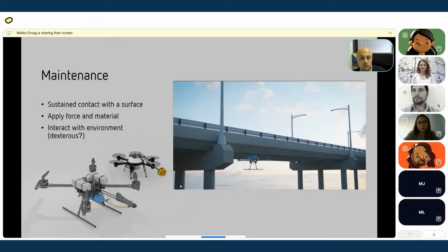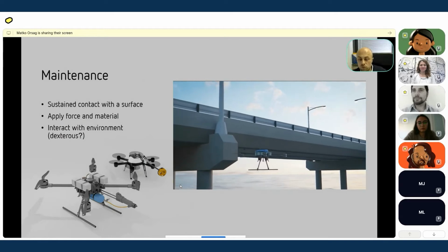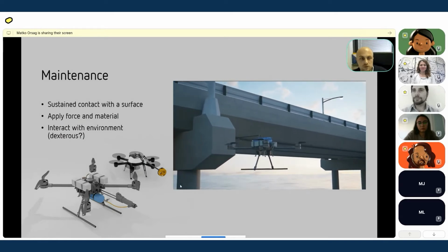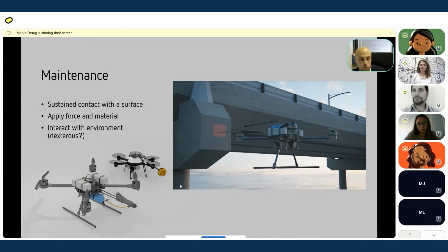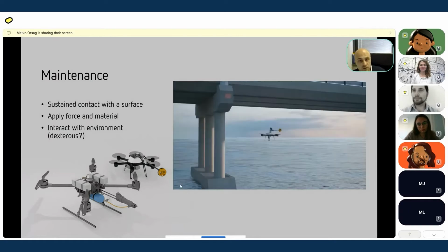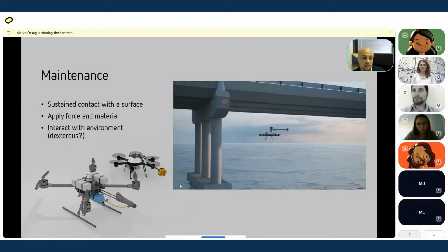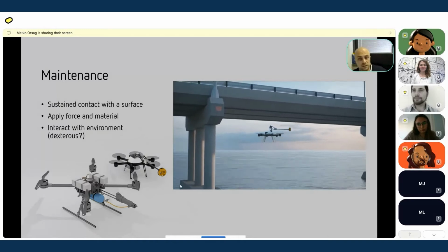So if you combine the localization with respect to the map of the infrastructure, then we can plot places where we want to put the sensors, and then we can have a team of UAVs working together to place them. You can imagine one UAV can go and place a primer on the spot, and then move so that another vehicle can come, fly up to that place, localize this primer, and then attach a sensor on it.